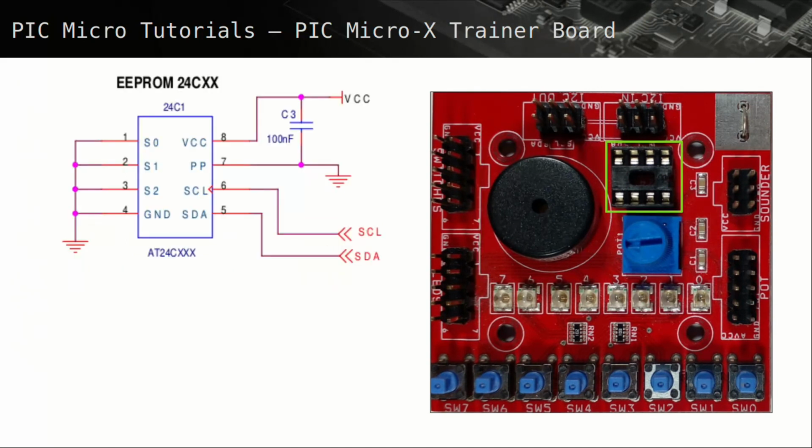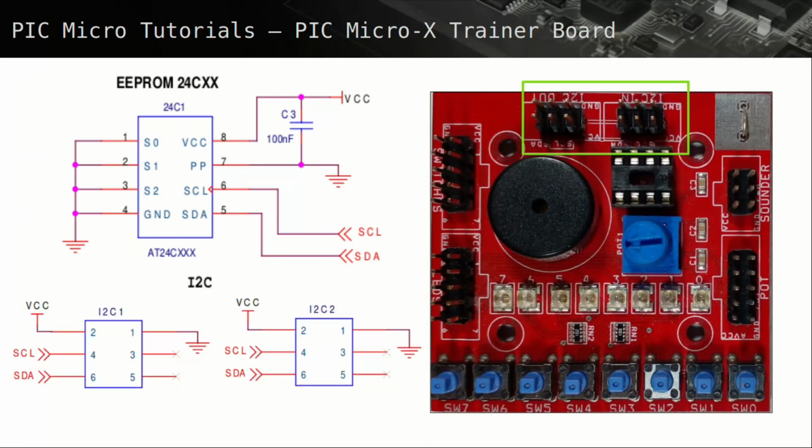The circuit for the EEPROM socket with a notch for locating pin 1 and the 2 I2C 6-pin headers. The 2 I2C header pins are connected in parallel but marked in and out, and to the socket. More details on this will be covered in tutorials later.